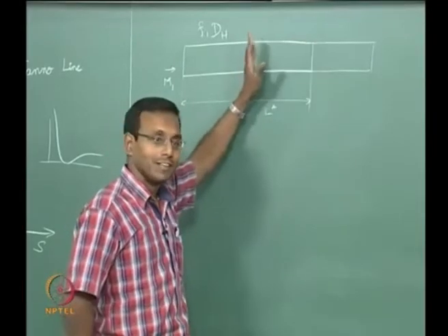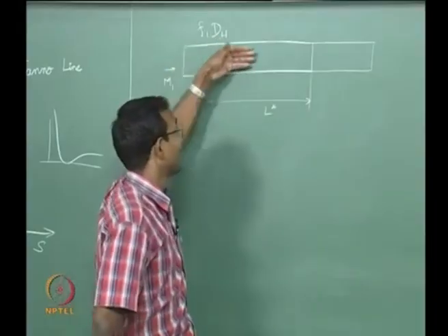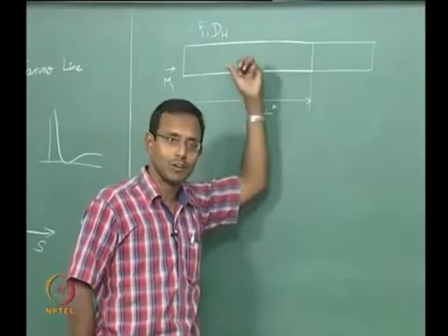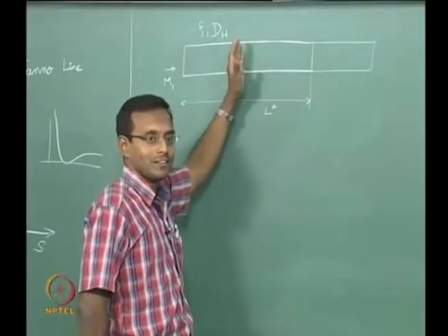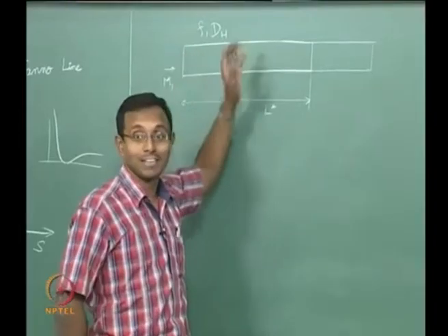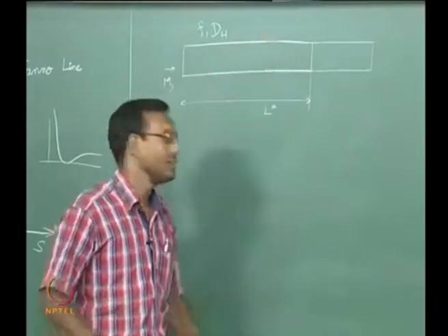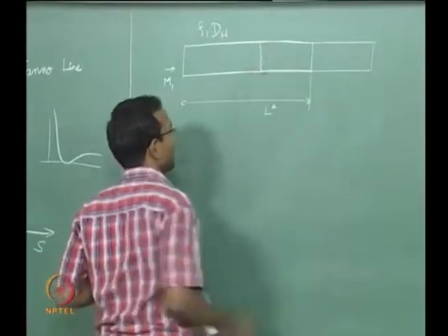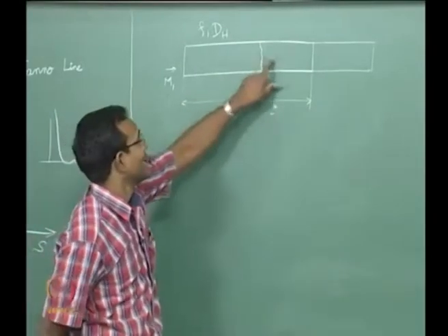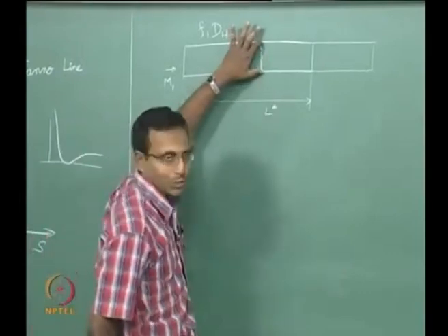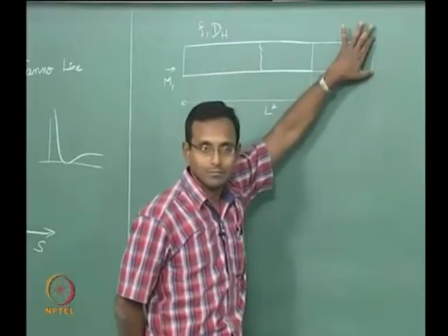and as it goes in, it cannot keep going in, because at some point Mach number will be higher than the Mach number of this shock. It is a moving shock. It will go and reach a point where the moving shock's Mach number will be equal to the incoming flow Mach number, and it stays there. Okay. So then I will go to a point where there will be a shock here. After that it is again 1D shock, right. So, it is going to be subsonic flow behind. Now, I have subsonic solution from here all the way to the end.